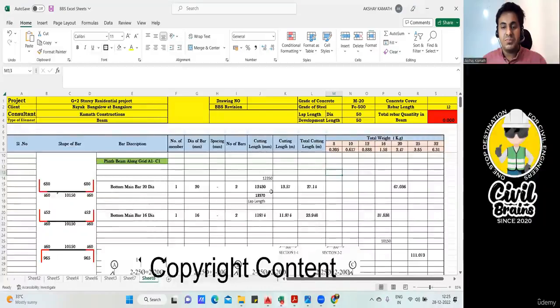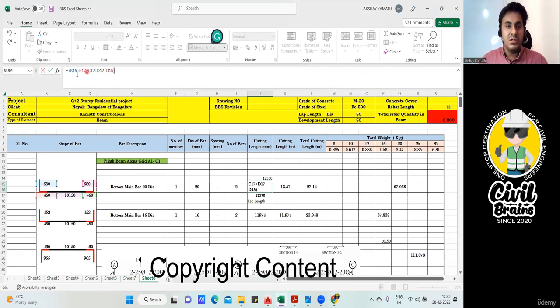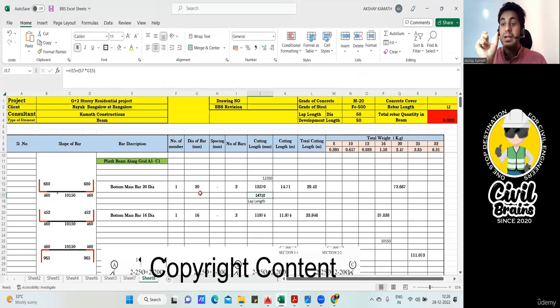So I'll go back to the Excel sheet. I'll take whatever length I've got and close the bracket here. So this is the answer we got. But since this answer is short, we need to add one lap length. So I'll write plus 57 into diameter of the bar, 20 diameter. So now this becomes my total cutting length, including the lap length. So my lap length is 57 times the diameter of the bar.